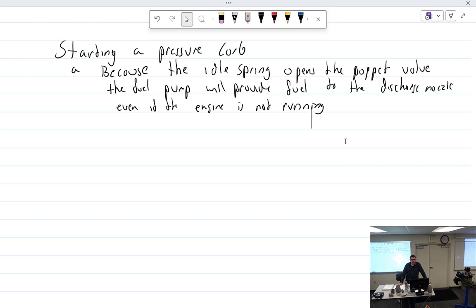That makes sense. Boost pump, and then it's kind of a hot start procedure. It almost takes 3 hands. It's kind of hard. So then I'll pull the mixture all the way back into idle cutoff, because as the starter's going, one of the pumps is then running off the engine. So I'll pull the mixture all the way back. I'll engage the starter with the throttle quarter inch open. If I don't get anything, I'll move the throttle up. Doesn't hurt it. I'm just adding more air.